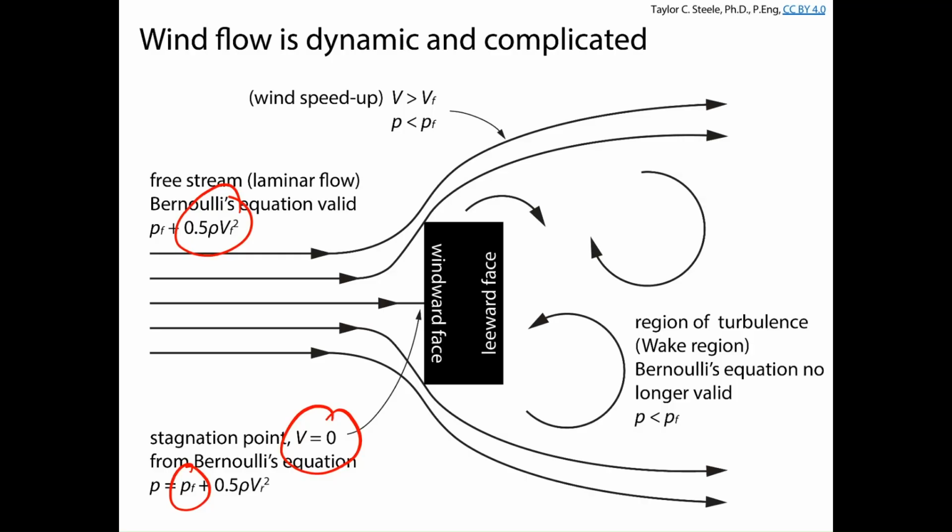Now, that's simple because we're basically going to say, okay, we've got a velocity of wind that's hitting the structure. The pressure is proportional to whatever the velocity is squared. Okay, so we'll talk about measuring wind velocities and how we can figure out what those might be.